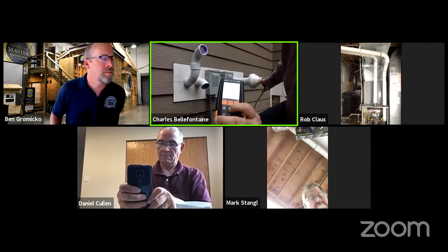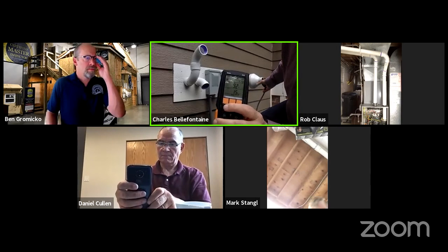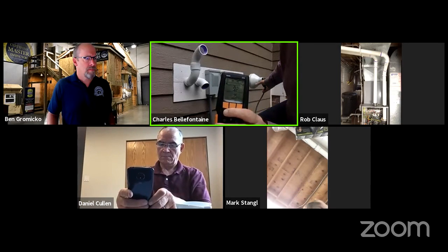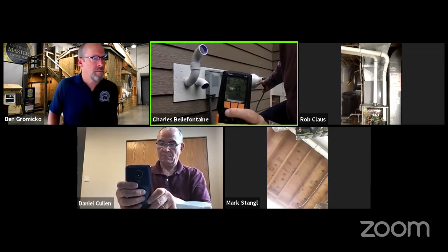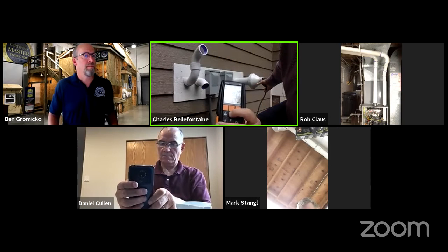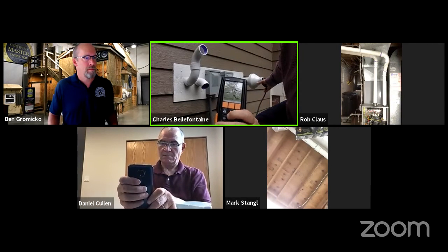With oxygen levels, if they're too high, and if you think about it, I've got a burner, and then it goes through the heat exchanger. If I have a hole in that heat exchanger, it's going to add additional oxygen after the fire, so that's going to get that level up there. We can also scroll through a few other readings on here. Let's see what we got.